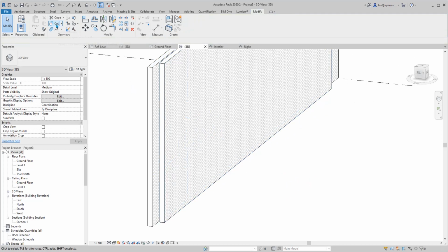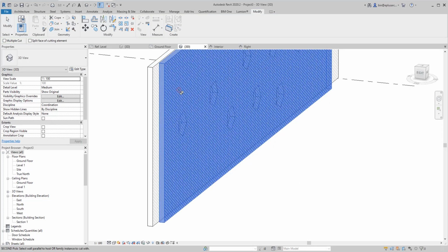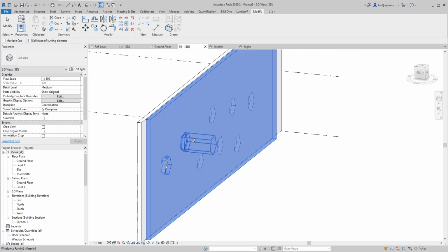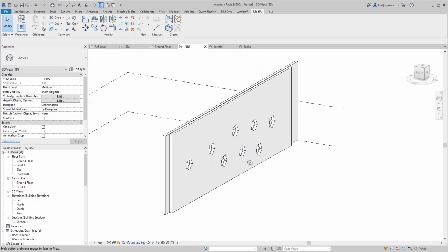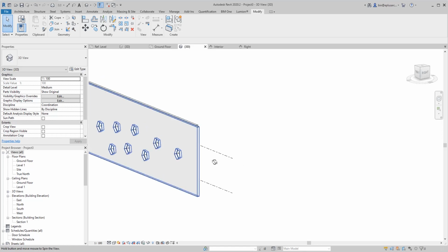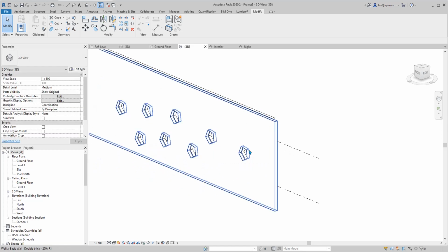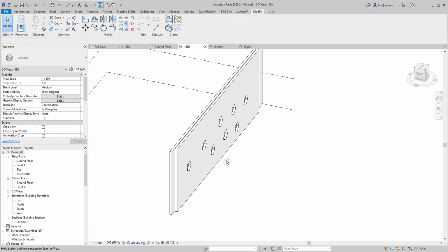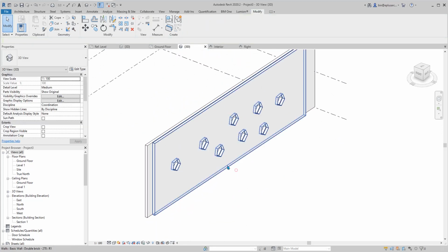So what you can do is cut this wall and then click this. You need to manually cut these holes for each window. If you don't cut, it won't. Sometimes, if there are too many, it might take a while, but manually doing this is a good way to avoid problems. Some people like it and some don't.